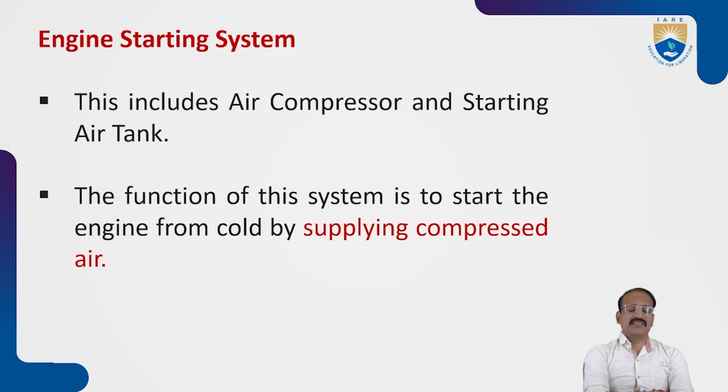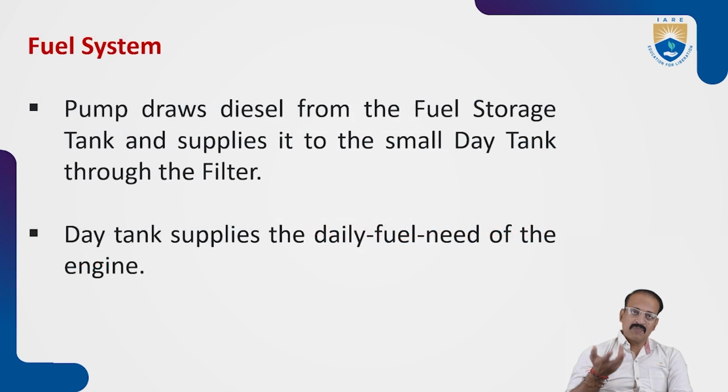Engine starting system. There is a starting system for any engine. This includes the air compressor. Already we have discussed in the diagram the air compressor and starting air tank. These are very important. The name itself is starting air tank. The function of this system is to start the engine from cold by supplying compressed air. Generally, the engine will be cold, so that's why this is needed.